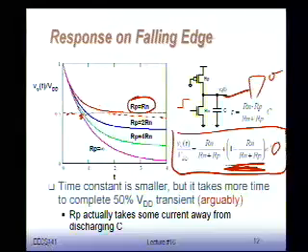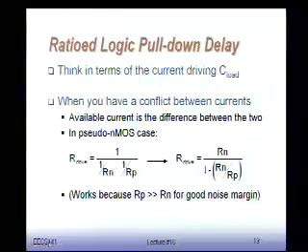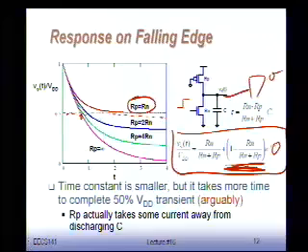Okay? Now, if you take the other argument, it says, well, it's going to be between 0 and VDD. Actually, you can see that the reason this gets slower and slower is that the smaller I make RP, the more I take current away. I'm basically trying to pump current out of the capacitor, and this PMOS keeps on pumping current back into it. So they're fighting each other.